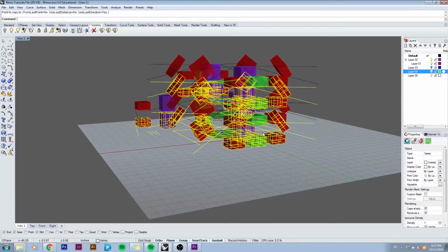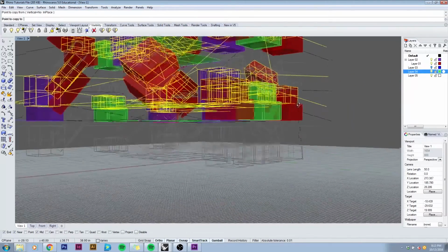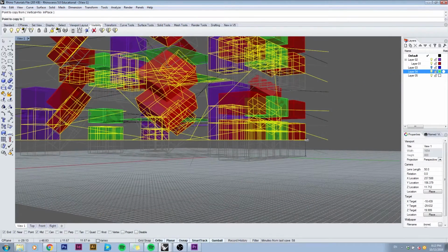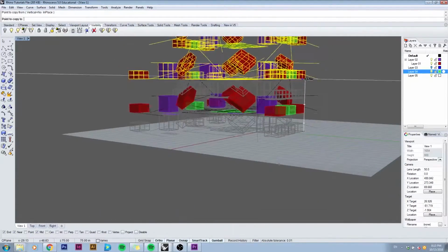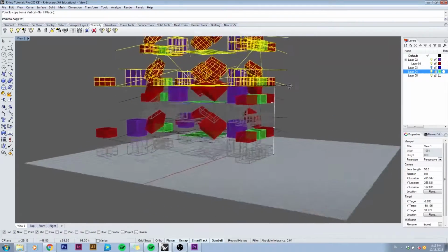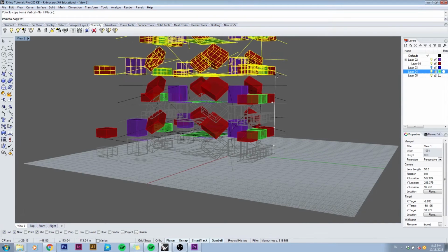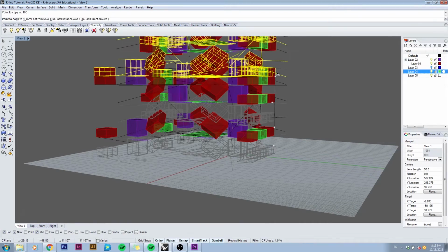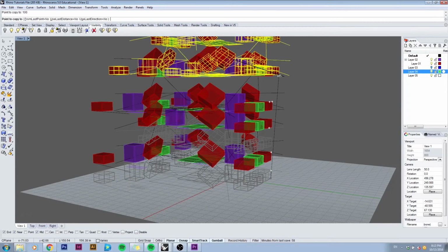Alternatively, as you remember, I can type in copy, pick a reference point, and then hover over my next reference point, which is this endpoint, if I want to move vertically. And without clicking, hit Tab on your keyboard, this will lock my movement only in this vertical space. Then once I'm happy with the distance, if I'm eyeballing it, or I could just input a specific dimension. In this case, I'll input 100. I can copy this object more over, or I can just click escape to exit out of this command.